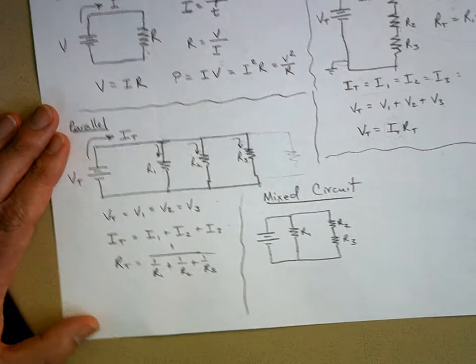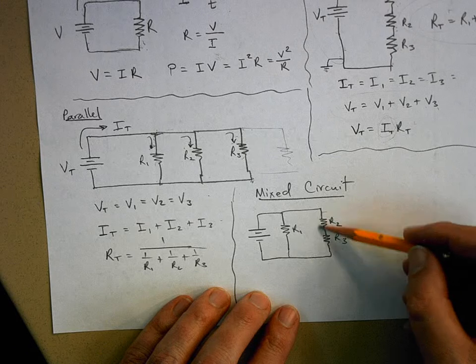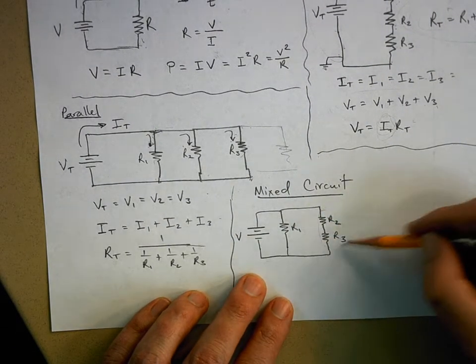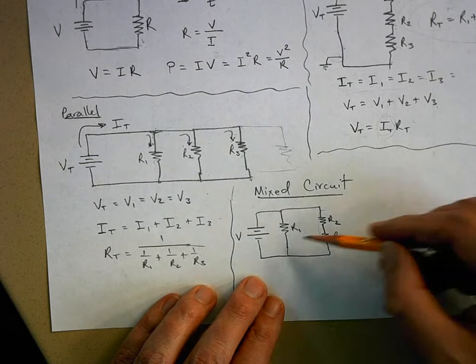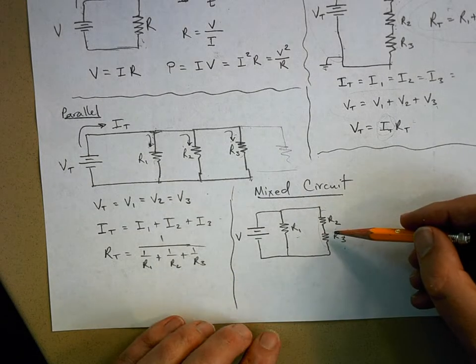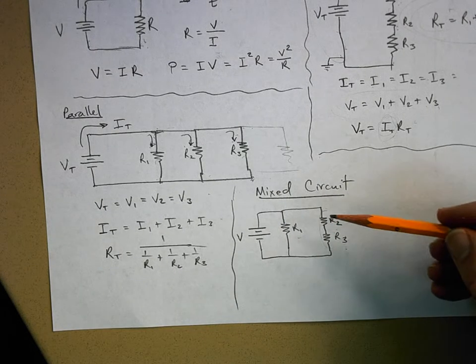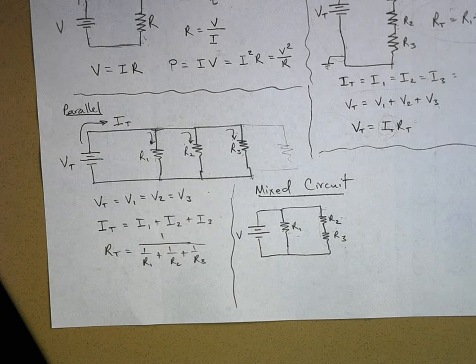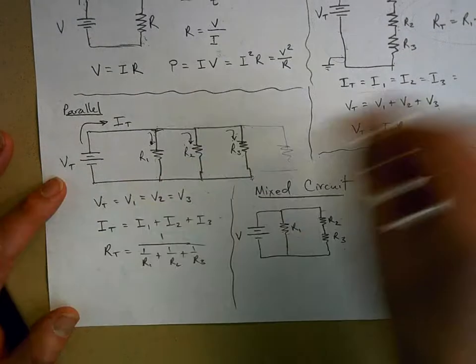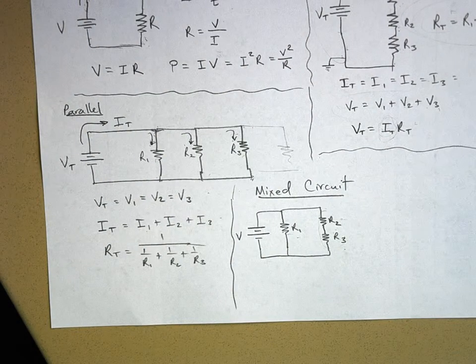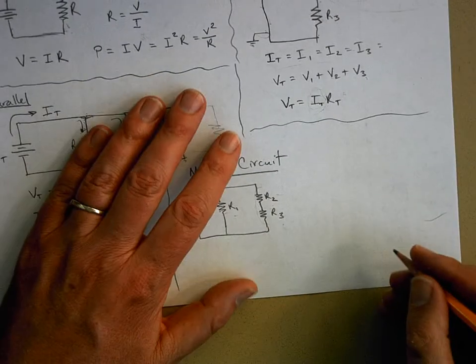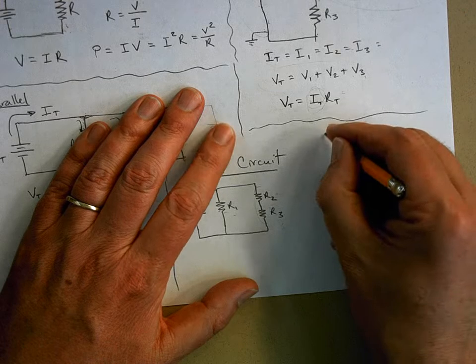Okay, and the way you think about these is, here's the voltage. If you combine these into one, they're in series, so you combine them. Yep, R1 and this. Then you treat these two in parallel so you can get the overall equivalent resistance. Then you can get the total current. Then you could just use all these little tricks that you learned before to solve the circuit. And we'll practice that in a little bit. But I do want to make, in the 3 minutes I have left, a quantity chart.